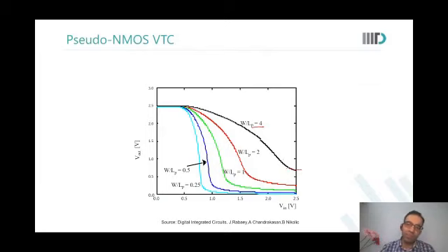Not very interesting, very complex, in the sense that while we save area, we save a lot of area actually. All the PMOSs are gone. So in that NOR gate, imagine if the NMOS is sized 1, the PMOS would have been sized, it's a 4 input thing. What would have been the size of the PMOSs?